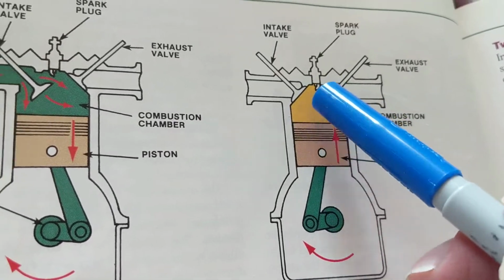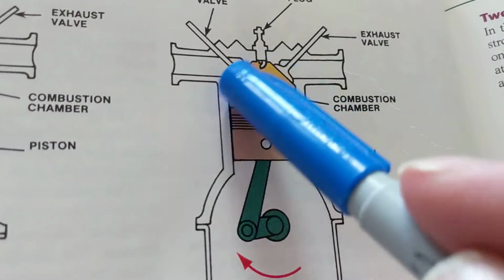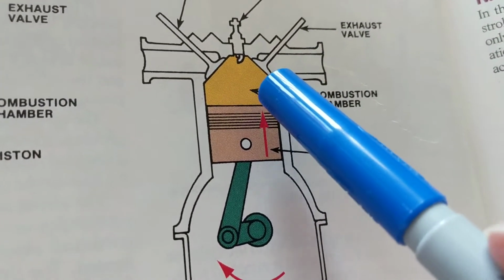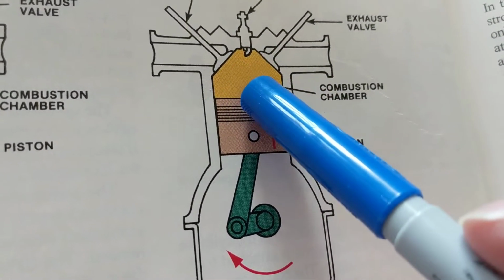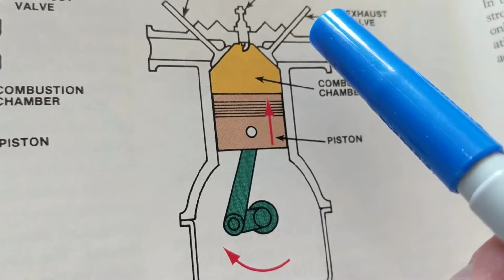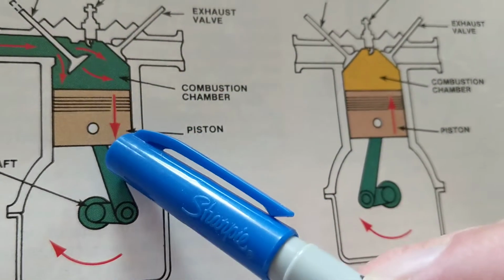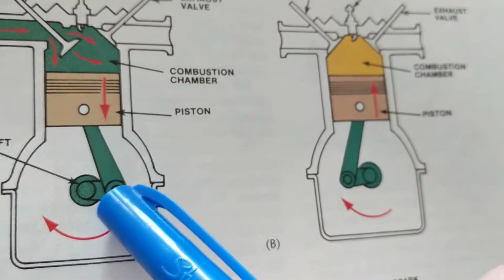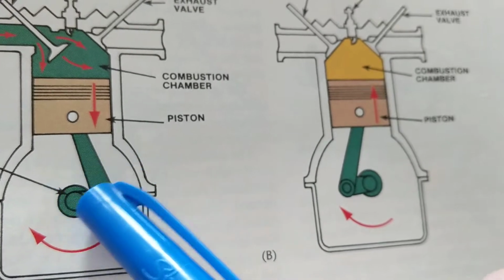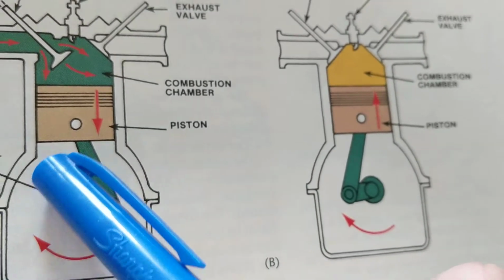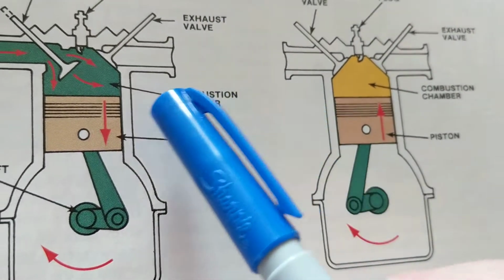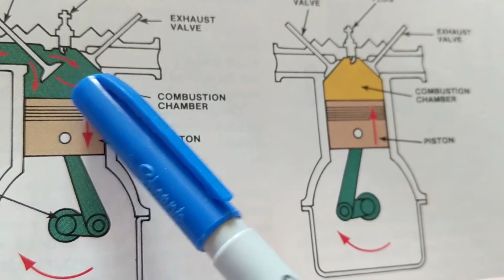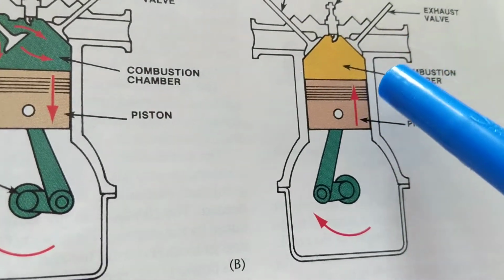We get as much air and fuel squeezed into this chamber as we can. Why? That will increase the pressure. That will increase the temperature. Then he comes back up. He was down at something called bottom dead center, where it goes all the way to the bottom. Then because of this rotary rotation, it has to swing back up. When he swings back up, guess what happens? This is closed. The air and the fuel are already in here. Now he's going to squeeze it.